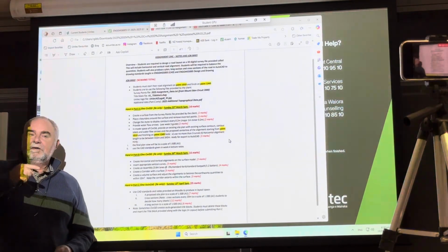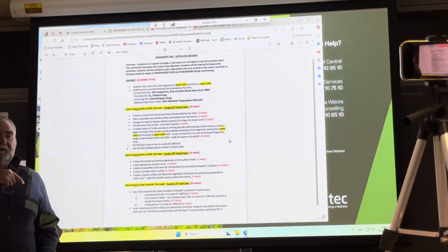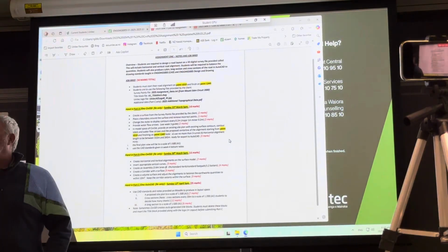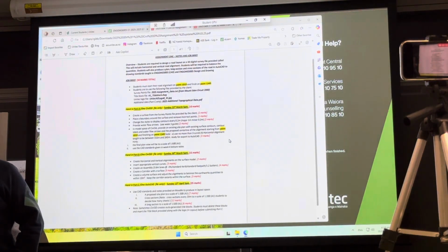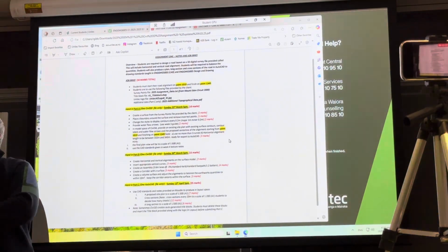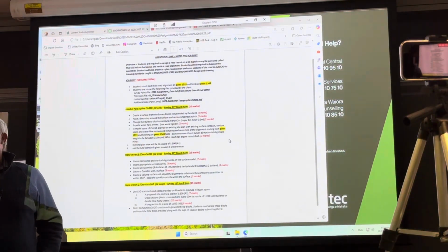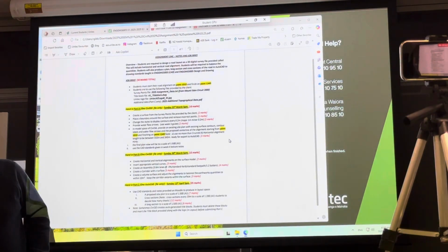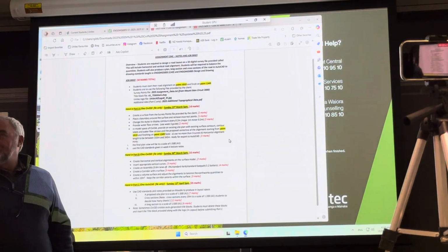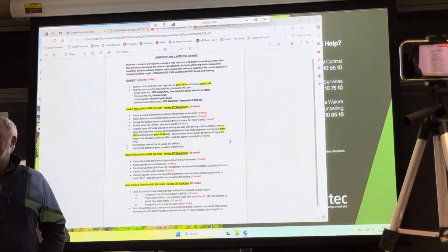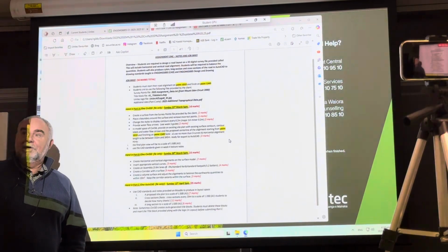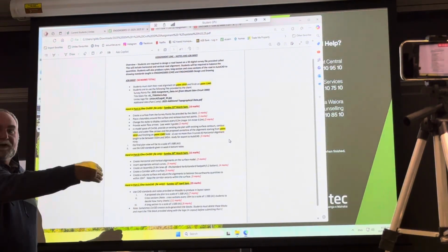And just remember, they need to be in order. Sheet 1 should have chainage 0 to whatever, and then you pick up from that on sheet 2, and finally on sheet 3 or 4 you keep going in order. You don't just grab the cross sections and put them all over the place, okay? In the old days we used to print them out, put them on the floor and get down, believe it or not, on our knees and have a look at the road design as it went along the cross sections, because that was the best way we could do it. And that's actually how they make movie files of cross sections as well. They have them in order as you're driving down the road.